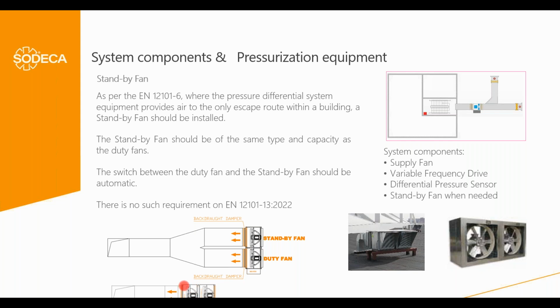Here we don't need the backdrop damper or a lot of space. It's simple, but be careful, because a fan that is not operating creates a high pressure loss in the fan that is operating, called idling loss. In that case, both fans will need bigger motor power if we install with this consideration.